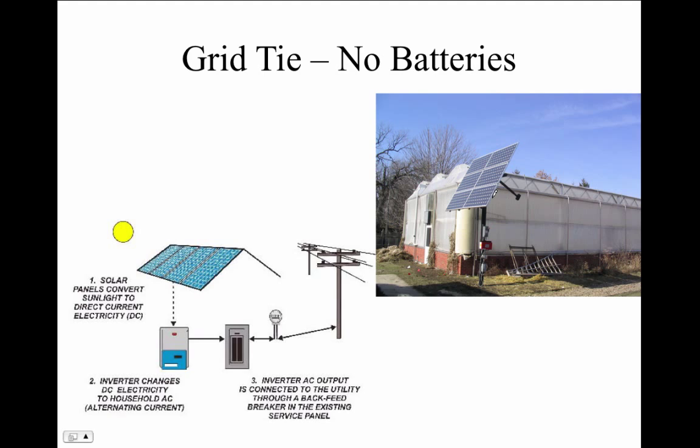I designed it. It's over at the Maharishi School. And this is the solar panel. This is the inverter. This is a safety so that you can disconnect the solar panel if you're working on the inverter. And this is a safety that allows you to disconnect the grid if you're working on the inverter. So it's conceptually very simple, and you can really see the whole layout here: solar panel, inverter, disconnect on the solar panel side, and disconnect on the grid side.